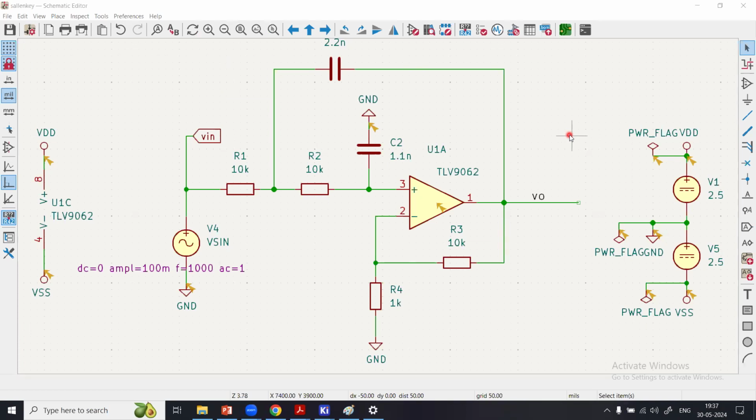And in the previous module, we just saw how we use this circuit to design, simulate and analyze the behavior of the Sallen-Key second order low pass active filter. We call it second order because the transfer function of this filter topology yields two poles in the complex S plane. And it's an active filter because we are using an operational amplifier. And it is low pass because we have seen the behavior of it as a low pass characteristic.